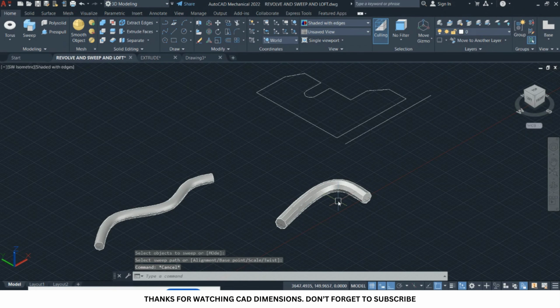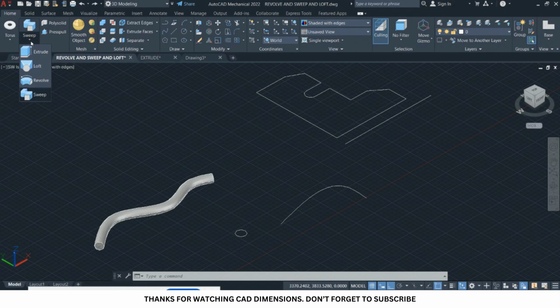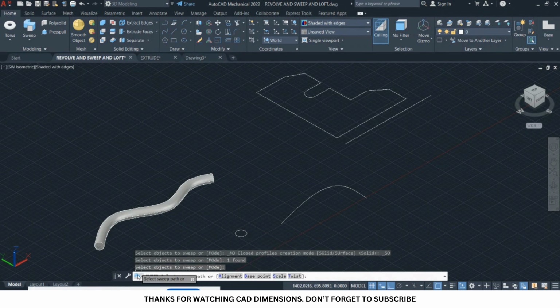Now there's another interesting thing you can do with the sweep, that is you can also create a twist. So let's see how we will do that. I'm going backward one step. Let's go back to the sweep. Again, select the sweep, then I select the closed shape, press enter. And if you look at the command, you see base point, scale, and twist. So we have the twist.